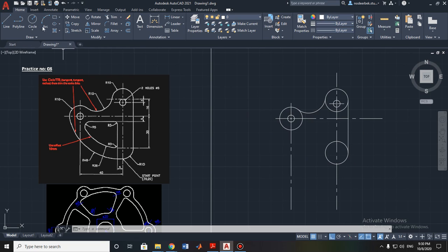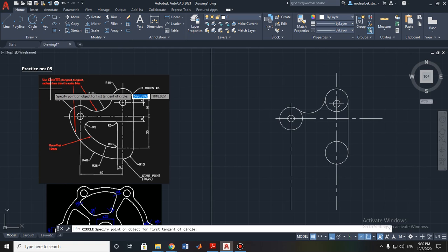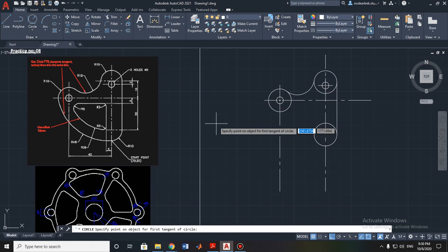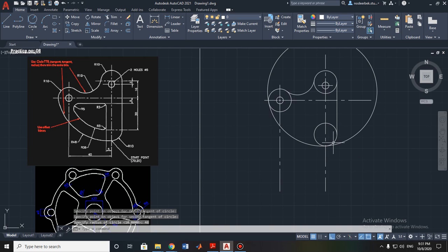In this case, we will choose the tangent radius tool. So if we want to build an outer fillet, we need to choose the tangent from here, and then I think from here, and then we need to put the amount of radius. Let's do this. I want to choose first here, and then from here, from another circle, and it asks us to put the size of the radius, which is 48 millimeters. Done. As you can see, we finished our action.